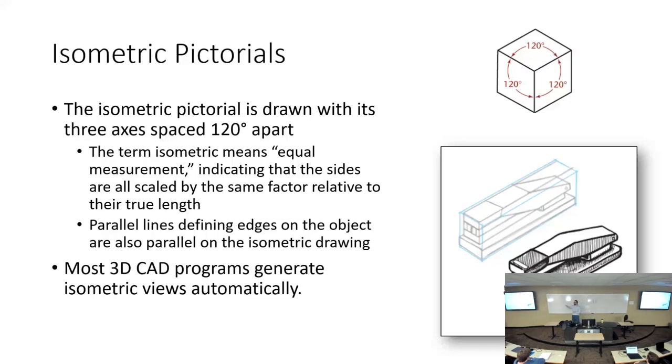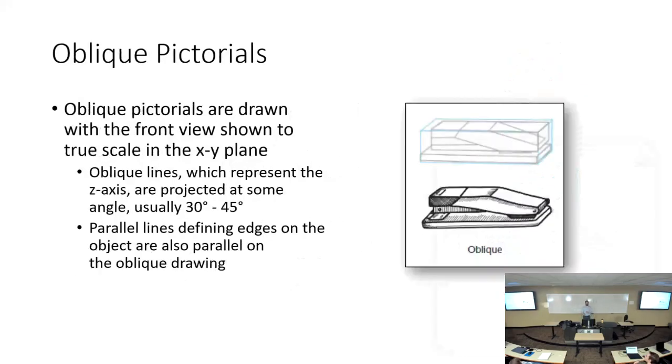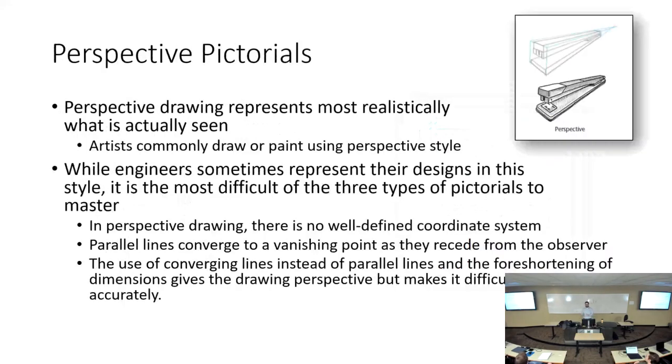Conversely, that's why we don't like to use perspective images. Do they look better? Yeah, they look better, but they don't maintain mathematical scale like an isometric view does. Either an isometric pictorial or an oblique pictorial works where scale is maintained. And that's really where a perspective pictorial fails. It looks good, yeah, it looks great, but it doesn't maintain scale, okay? So that's why we don't use them very much in engineering drawings. Does that make sense? Okay.